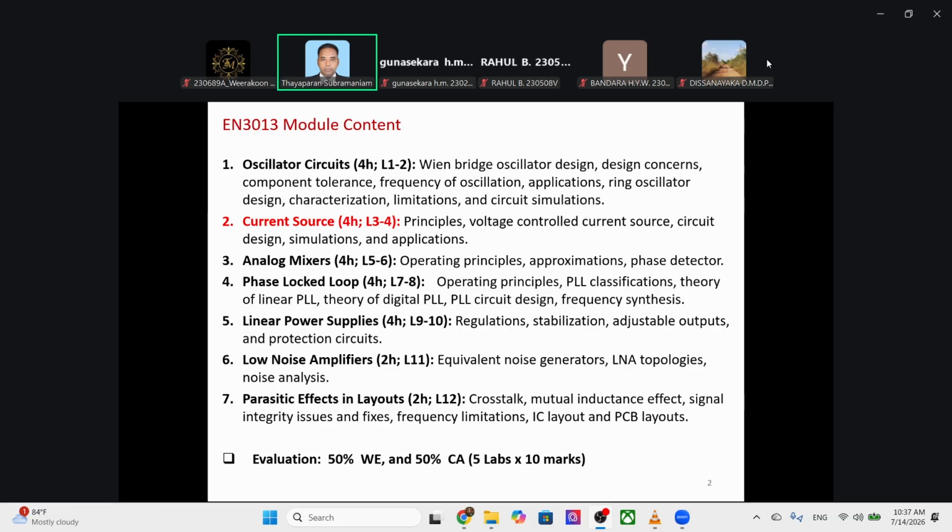Generally, I'm not sure whether those facilities are equipped in our lab supply voltages. Depending on the supply voltage equipment, there are sense pins. That means if one supply and the sense pin are also connected to the same point where we want to give the supply, what happens in the sense pin is the supply voltage will keep increasing until the sense pin's voltage is the desired voltage, or the voltage that we set.